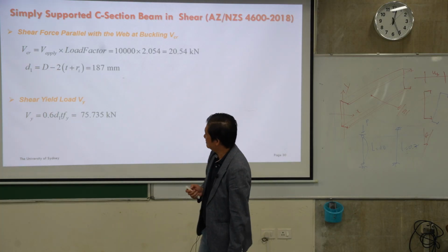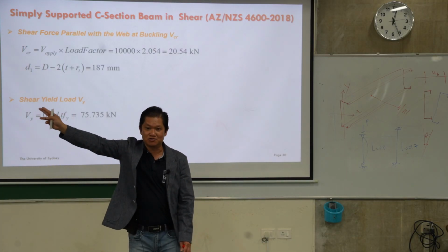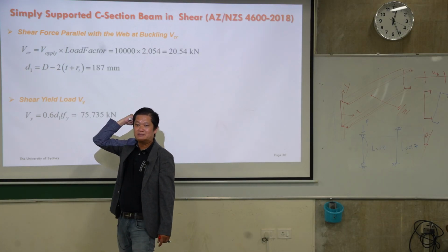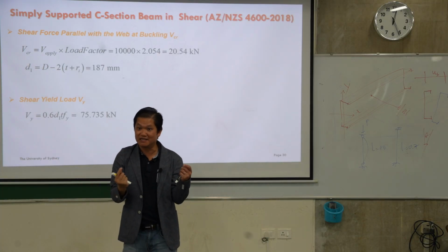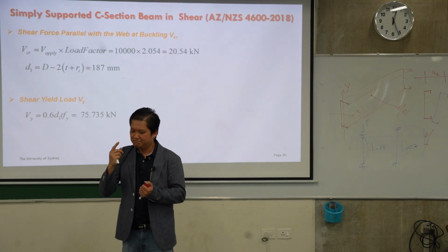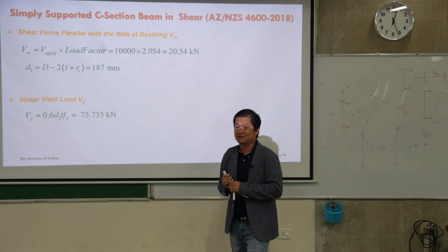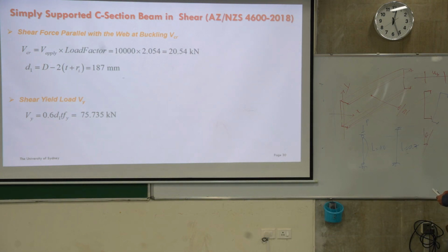The stress? Stress in here, we bypass that one by going straight to load. So you get a load factor at the minimum point, you times it with the load that you apply at the beginning, and you get the buckling load. Buckling stress, you found, very good question. It's a little bit tricky with shear. I'll tell you why. You can work out the stress, and you times it using the Kv, that's Timoshenko. The problem with that is we need to bypass it.